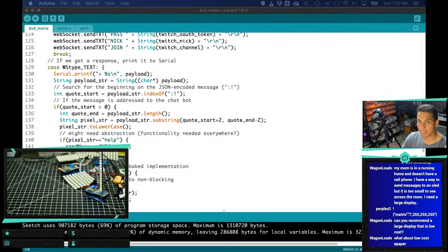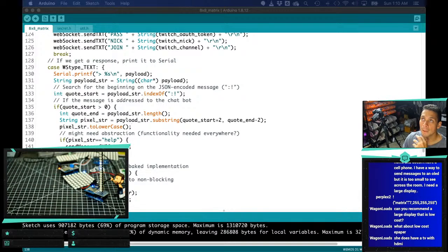The e-paper stuff gets pretty big and works with microcontrollers. I think the biggest one I've seen is 7-inch, maybe 10-inch, of the e-ink, e-paper, and that's very nice and has a very high contrast. So if you don't care about colors, then you're going to use e-paper. Those get pretty pricey, so that's why I would say an LCD.